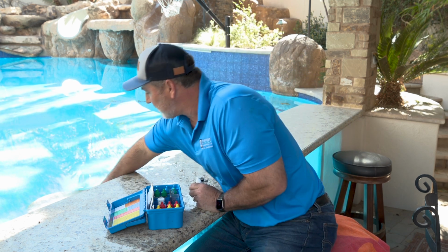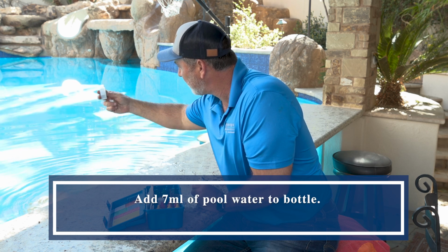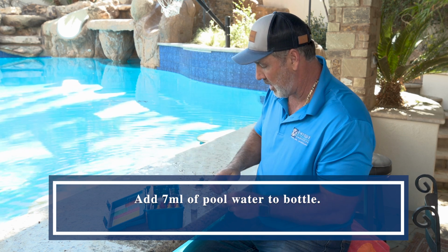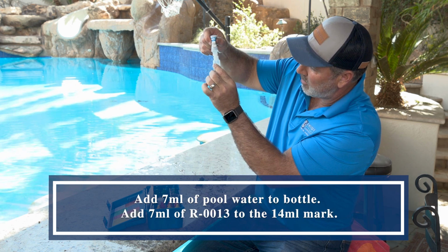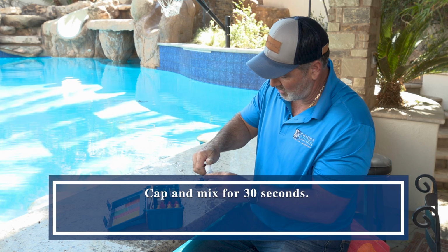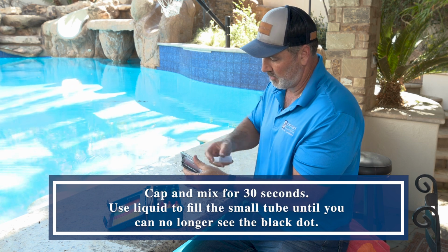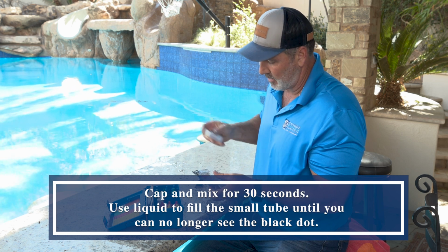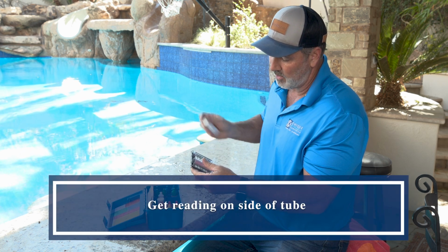Going into testing, so where is my cyanuric? How well have I been keeping this up to speed? So I want to add 7 milliliters. I'm going to add my reagent, 7 more. Okay. And we're going to agitate and shake this for 30 seconds. And then we're going to add it to this tube here. And when we look in, we'll see a black dot in the bottom. And you add this until the black dot disappears. When it disappears, you're going to read the reading on the side.